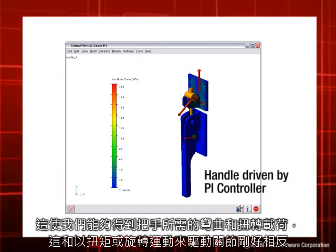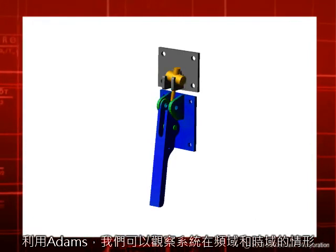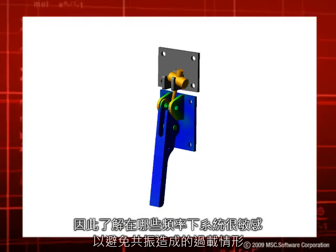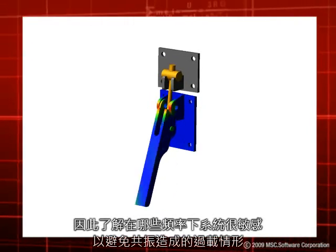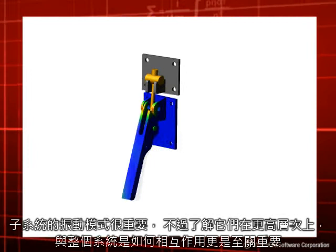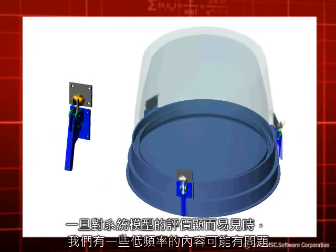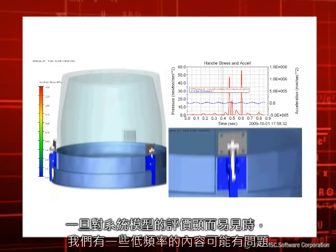With Adams, we can look at the system in the frequency domain as well as the time domain. Because inertial loads due to vibration can be significant, it is important to understand what frequencies this system is sensitive to in order to avoid excessive loading created by resonances. Subsystem modes of vibration are important, but understanding how they interact at a higher level with the entire system is crucial. Once evaluated in the system model, it becomes apparent that we have some low-frequency content that could be problematic.